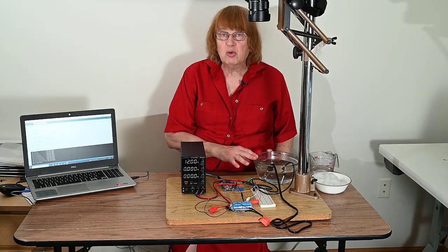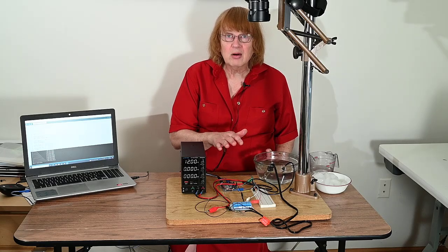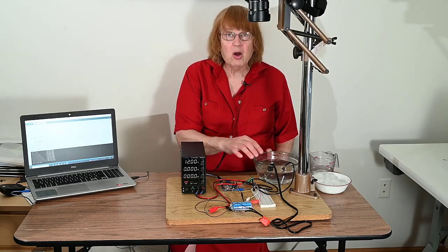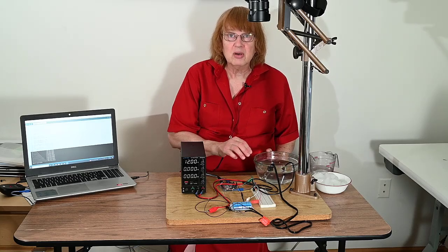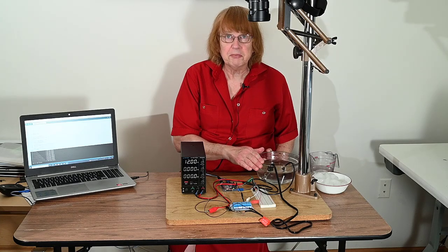So we've seen that the water bath controller is a good example. We saw software that implements bang-bang control. We saw an analog input from the temperature sensor. And we saw how to control high voltages and currents with a digital output and some additional circuitry.